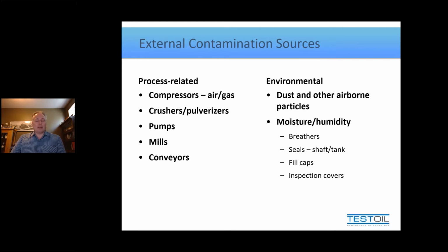But even if we're operating what we consider to be a relatively clean environment, because nothing is happening of any great consequence outside of the machine, just general airborne particulate and humidity can be drawn into the machine. And of course, this can happen through any means necessary, any opening into the system. So that could be something as simple as a fill cap or a breather or a dipstick, even things like big tank covers and inspection covers.